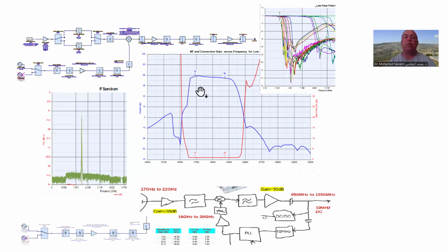And remember, the noise figure that we're trying to reach to be competitive is somewhere less than 1.5 dB. That puts a constraint that we have to have a front end LNA with a sub 1 dB noise figure. Then we're allowing a half dB for the rest of the system contribution and the waveguide to microstrip transition.